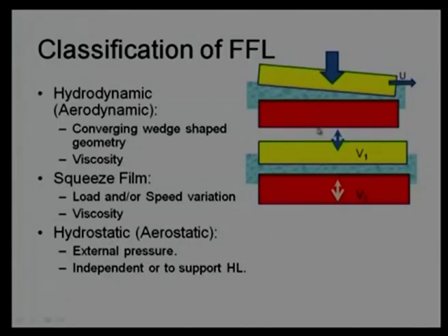Or if there is a load applied, which is initially maybe say 100 Newton and reduces to 80 Newton. Naturally, when the load decreases, this block will move up. If the loading increases, this block will come down, or say the film thickness reduces. So, indirectly even the load is going to induce a velocity of the yellow block. So, whichever the situation is, a squeeze film action will occur.